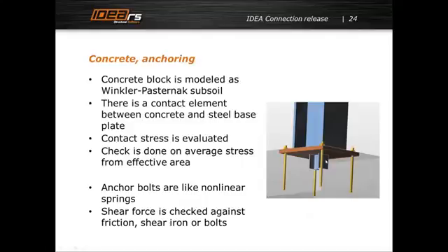Again, a little bit of theory. There is concrete in the joint, and we decided to model the concrete like Winkler-Pasternak subsoil, which is normally used for design of buildings. So if it works for buildings, why can it not work for connections? Only the stiffness of the material is different.